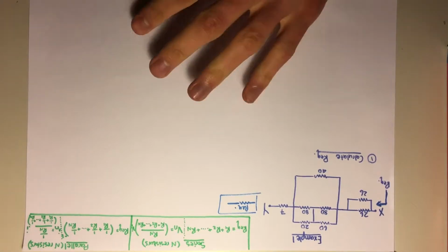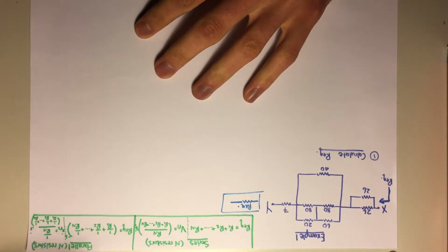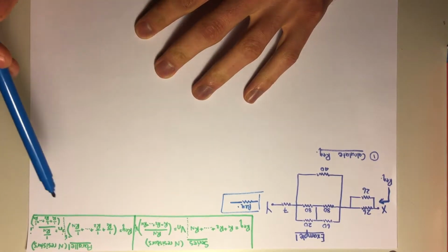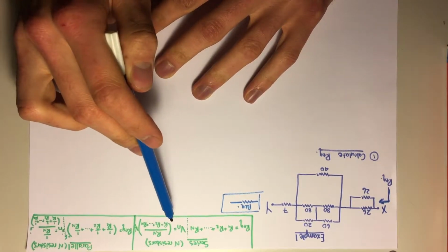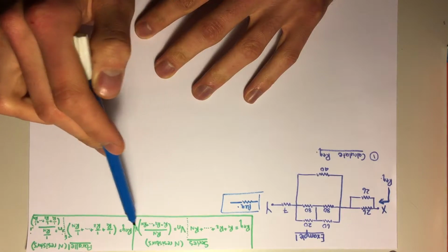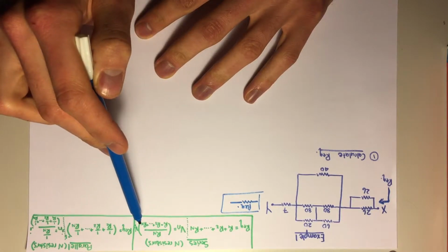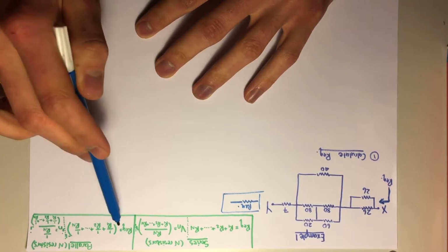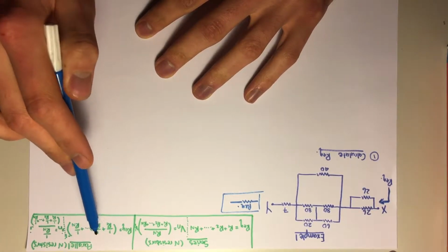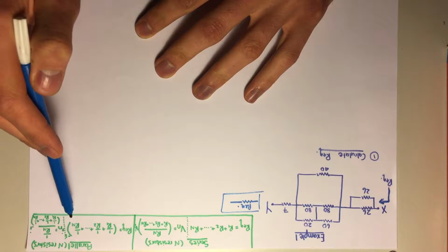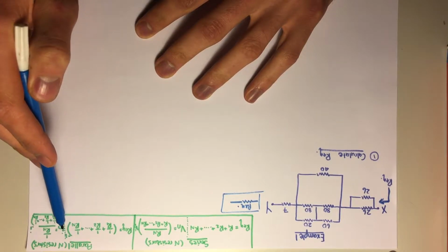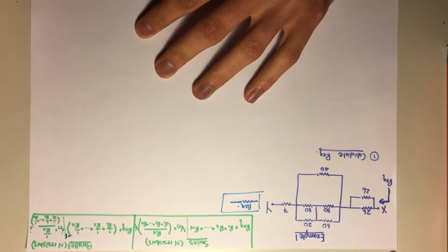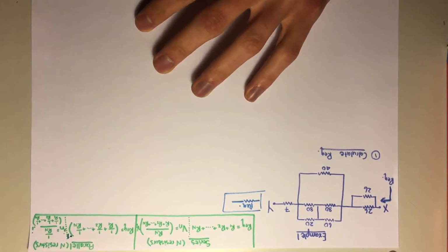Okay, so the formulae from the theory videos for series and parallel are given here. For series, the R equivalent is just the addition of all the resistances. The voltage over the nth resistor is the nth resistance divided by the addition of all the resistances times VI. For parallel, R equivalent is 1 over each resistance added all the way up to Rn, inverted. That gives you R equivalent. So in other words, to the minus 1. I don't know if you can see that.